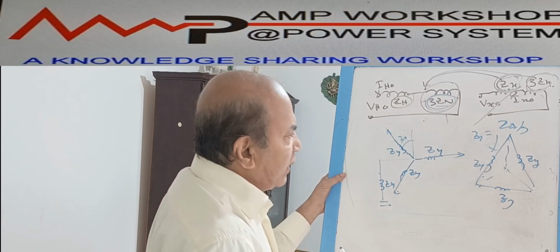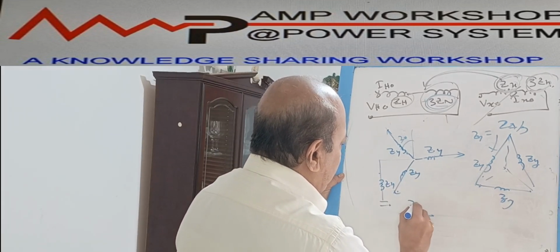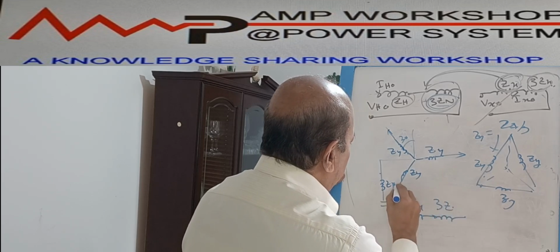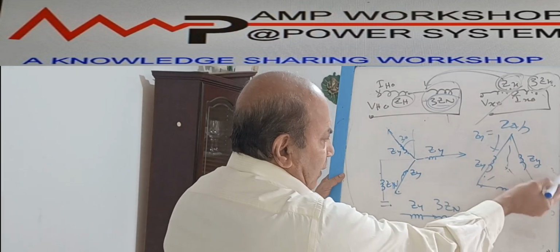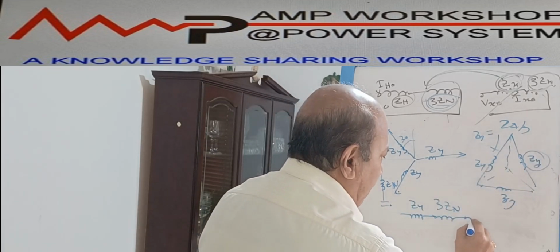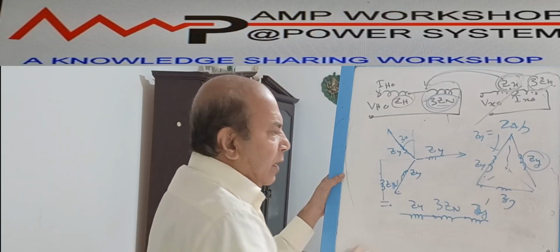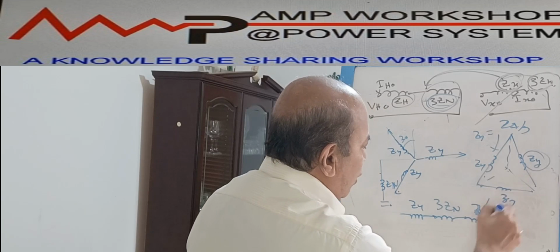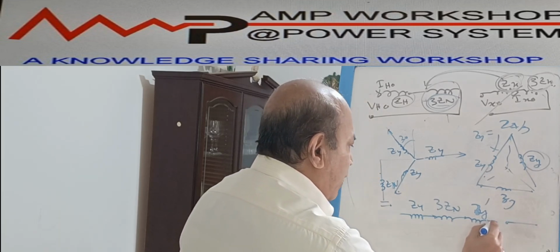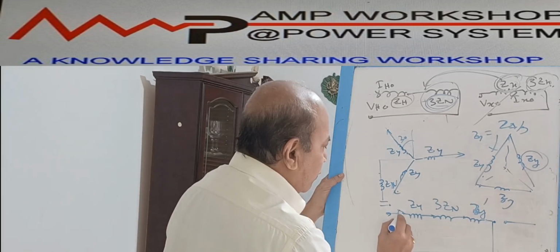Now if we go to the zero sequence network, the same way, that is the primary side. What will be the zero sequence network? Primary side will be Zy plus 3Zn, right? This capital A, 3Zn. Now when we transfer this secondary side impedance to the primary side, first you bring one phase over here, small zy dash, right. This is coming with the turns ratio. Then there is no neutral over here, right? If the neutral is not there, then this is open. Then it is going over here. From here, it is coming back. That is your V0, and the current is going through I0.